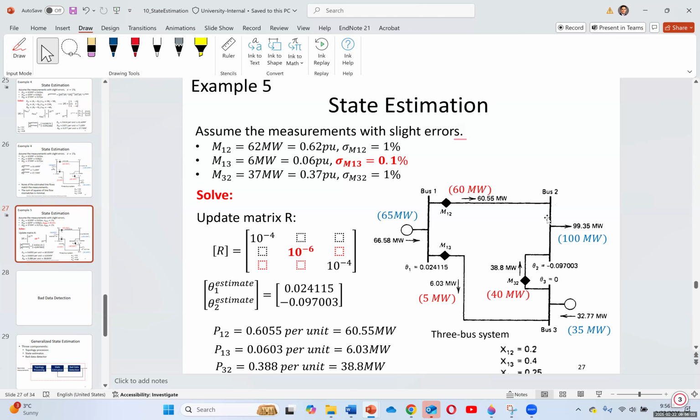Imagine we have 100 generators, 100 buses, and 100 meters, and also 10,000 loads. You can see that it becomes very complicated, and it needs a computer-aided system to be able to calculate this. Each of these has its own measurements and its own errors that have to be taken into account. Some errors are minimal, and we could discard them. Some of them are gross and large, and we can't discard them. And then we have what we call bad data detection, and that creates a problem. It could even be a cyber attack sometimes.